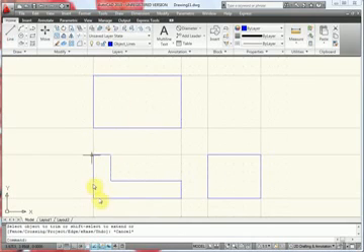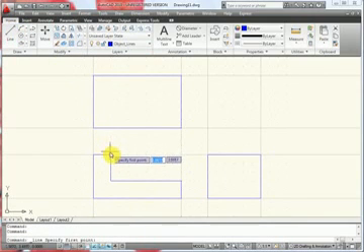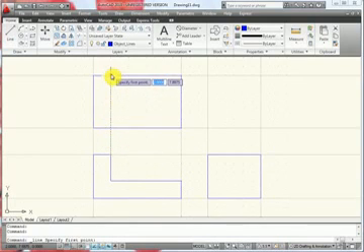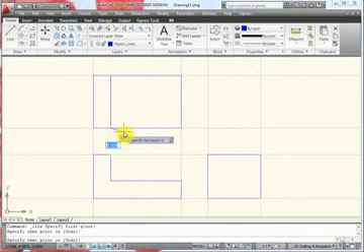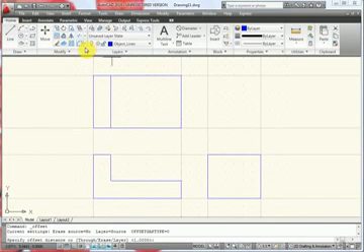And I'm going to start projecting some geometry from this front view up to the top view. So I'm going to grab my line tool, and AutoCAD has this thing called object tracking. So I just bring my cursor over a certain point, and it'll track that point. Notice how I have a little orange cross about that point, and I'll make a dashed line in a perpendicular direction. So I'm going to snap at the intersection of this top view, and then I'm going to bring my cursor down to this point again, and slowly bring it back and make an intersection of this top. Now I have another perfectly vertical line that lines up with this surface right here. Once we've done that, I'm going to offset a few lines in this top view at 1 inch.